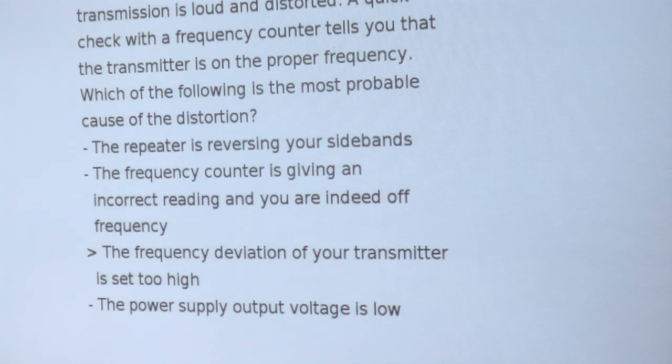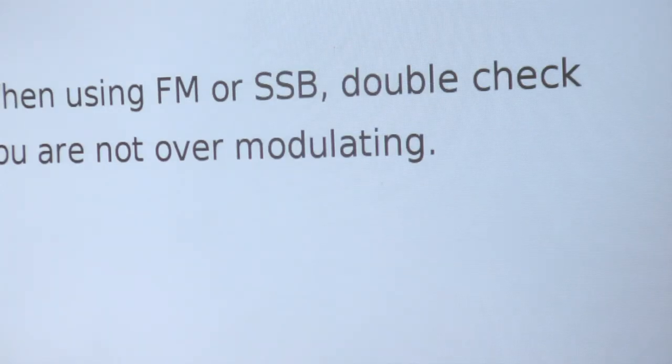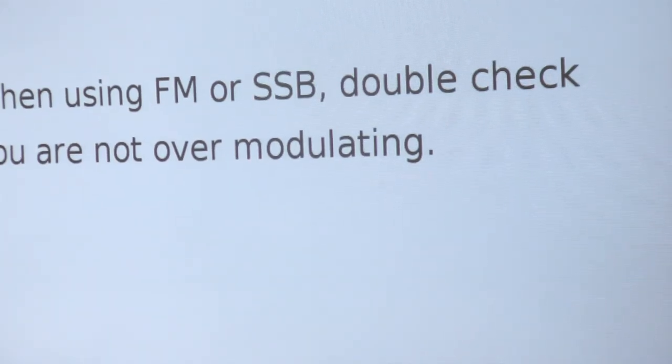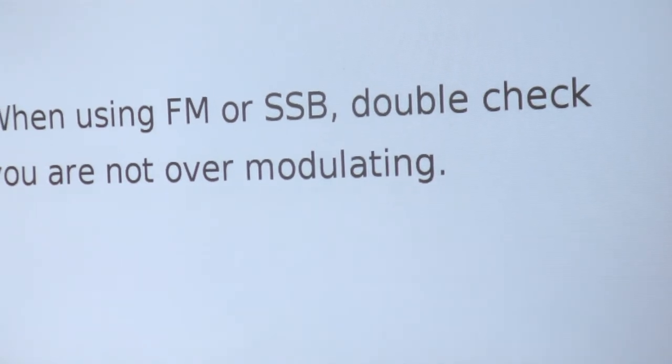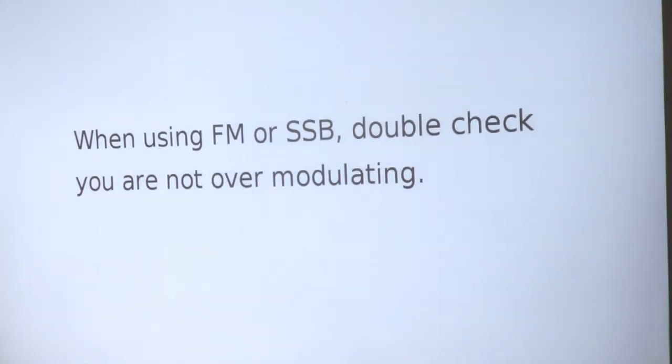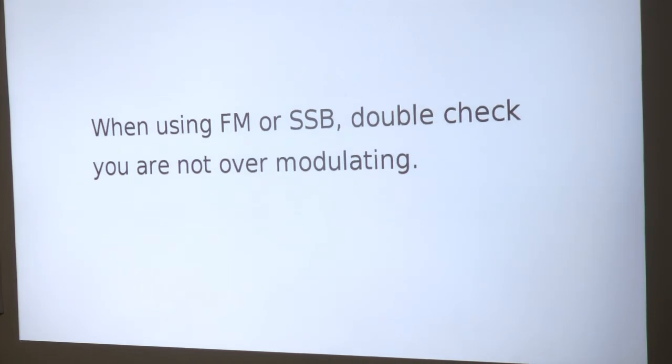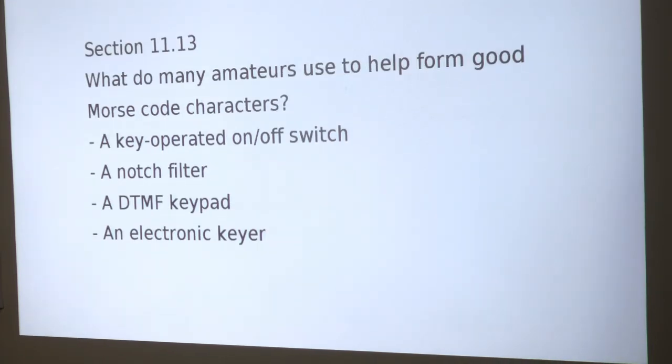Bingo. So when you're using FM or single sideband, double check that you're not overmodulating, so that you don't have the gain too high, you're not talking too close to the microphone, so that your microphone gain isn't set too high. Just a couple quick checks you should do.